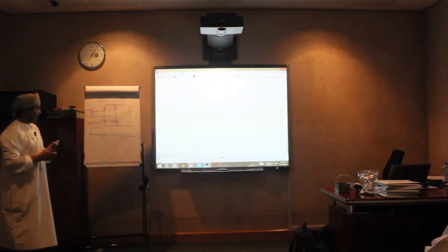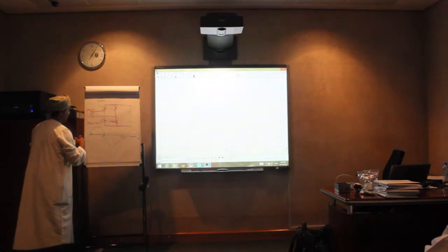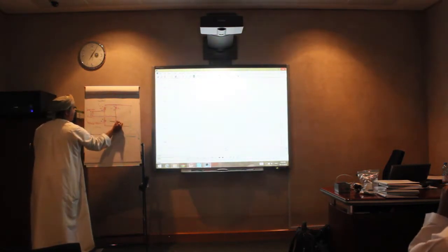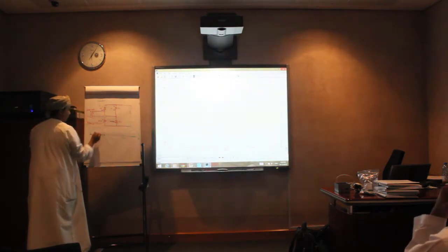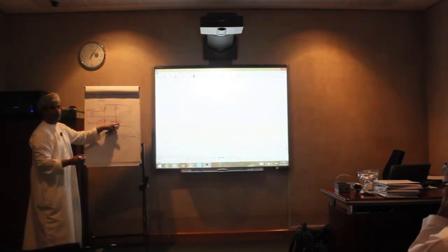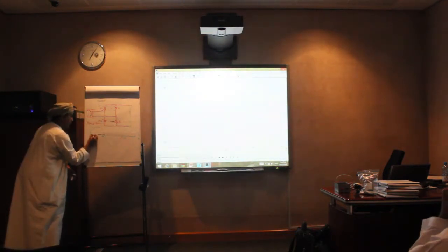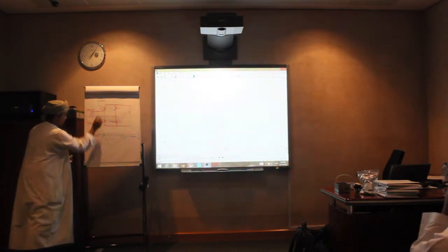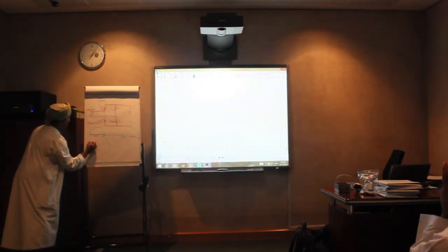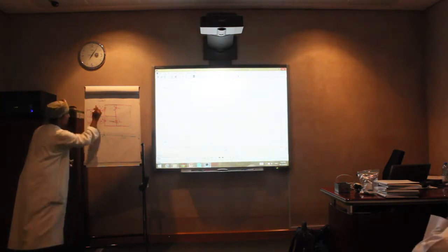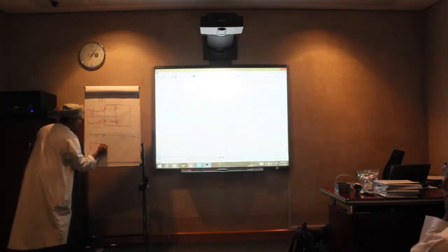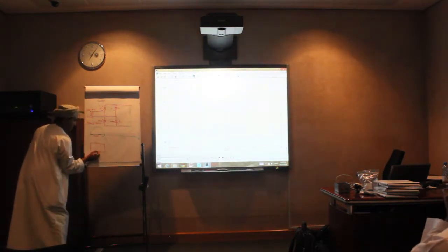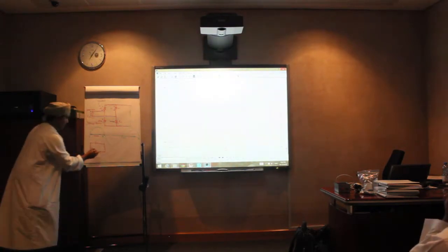So now, if I dot that one, I can call this one D1, D2, D3, and D4. So D1 and D3 are conducting, right? So in this period, D1 and D3 are conducting. If I block that circuit, which is this internal one, this is the first diode, which is that path, and then to the resistance, and then come back through this diode toward the source. So this is my circuit, right?